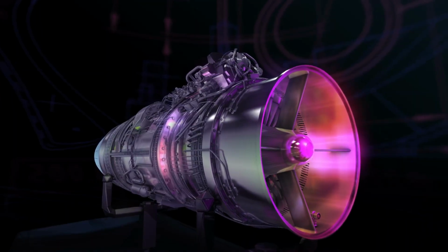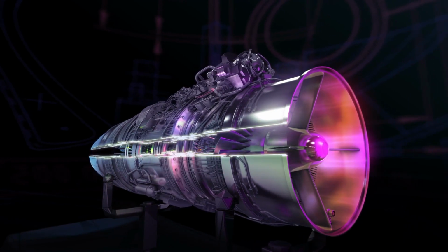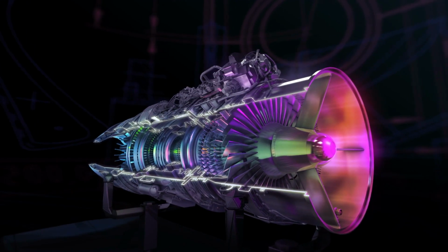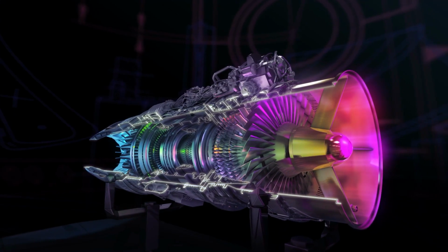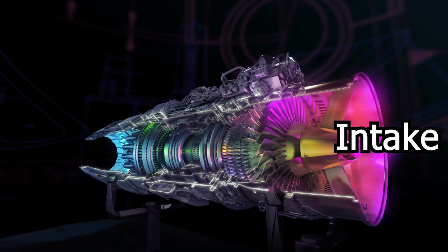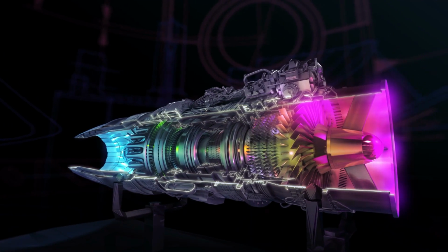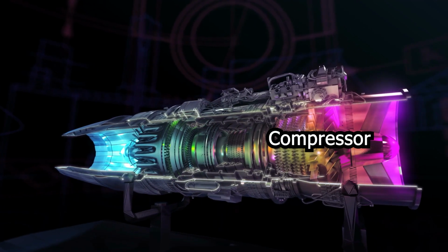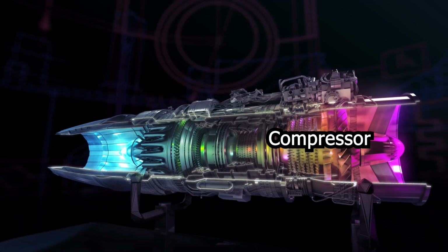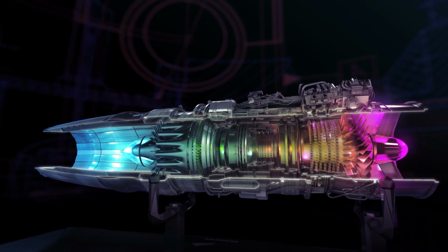In this cutaway video of a natural gas turbine, we can get an idea of the similarities to a 4-stroke internal combustion engine found in vehicles. On the right side in purple, we have our intake similar to the intake stroke of a 4-stroke engine, except there are really no moving components related to taking air in as the turbines open to the atmosphere. Once air begins entering the fan blades though, the air begins to compress, kind of like the compression stroke of a 4-stroke engine. The fan blades are exerting force on the air and that causes this compression as they go from stage to stage.